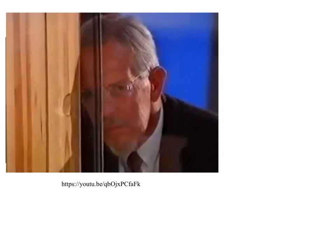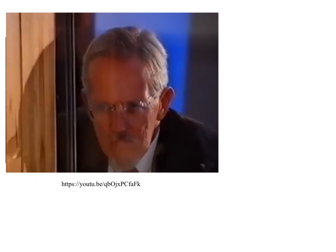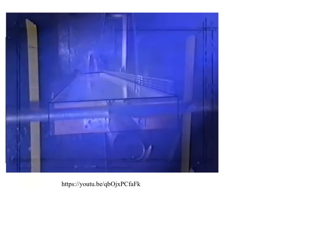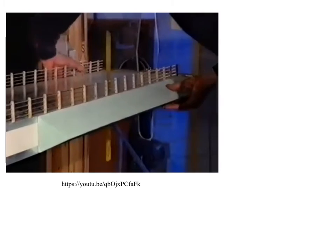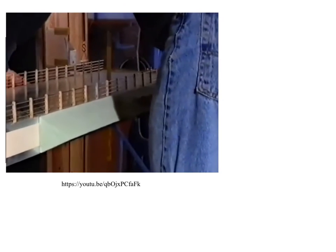This behavior could be replicated in the lab. For Gimsing, the answer could be seen in the wind tunnel. The problem with the Tacoma Narrows Bridge was its sharp, square road deck. As the wind hit it, miniature whirlwinds formed at the corners, which started the twisting. The twist turned the deck towards the wind, which produced more twist, and finally, disaster. The answer: get rid of the square corners.